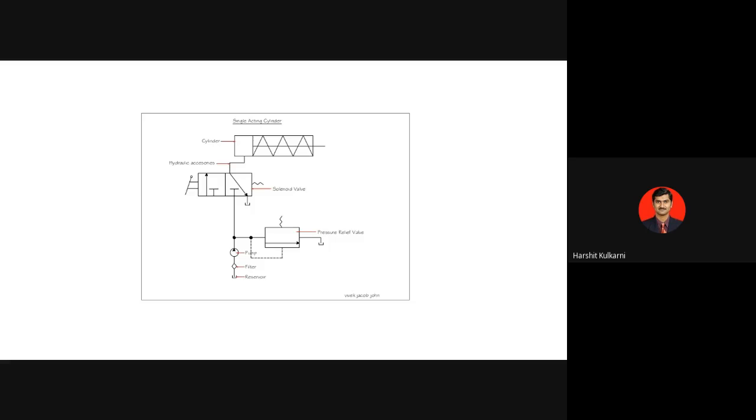See, this is how we are connecting from the last chapter to this chapter. You people have studied the pressure relief valve. So what is the pressure relief valve's function? You have to reduce the pressure when it is at the end of the extension stroke or at the end of the retraction stroke. I had explained this during my explanation of the PRV. Once the extension is completed, the pump will be on. If you remember, even during our experimentation, the pump will never be off.